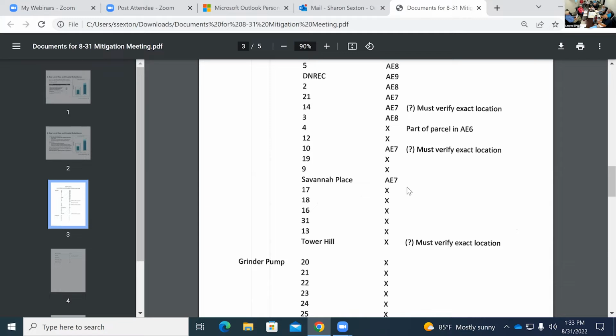You can say a minimum elevation of 10.6, because there are some elevation 6s. Minimum elevation of 10.6 or a foot above adjacent grade. Great, because then if you're already up at 15, you've got that foot above it for localized inundation, if it rains hard. That's what we've been doing, 18 inches of freeboard. Wherever it is, it's 18 inches of freeboard buffer.